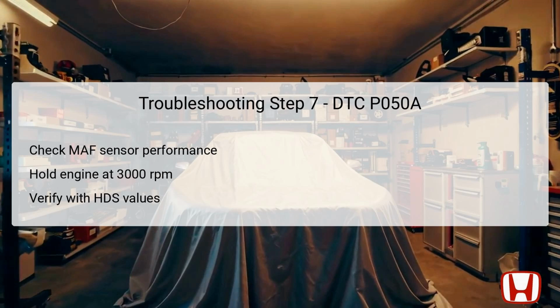If the readings are consistent with these thresholds, the MAF sensor is functioning correctly, and you can proceed to the next step. However, if the values don't match the expected range, then the MAF IAT sensor should be replaced to mitigate any impact on combustion and performance.